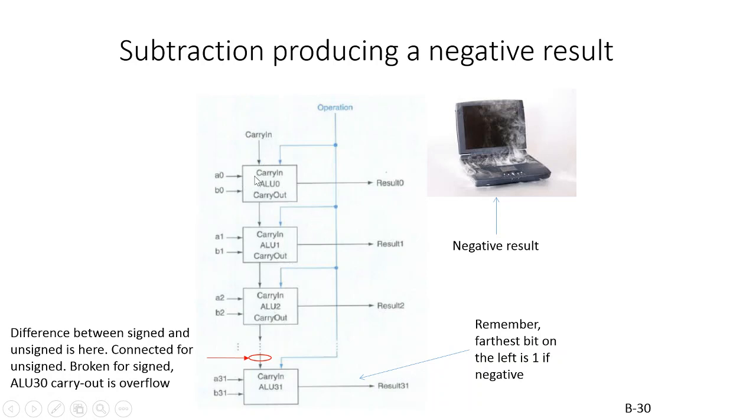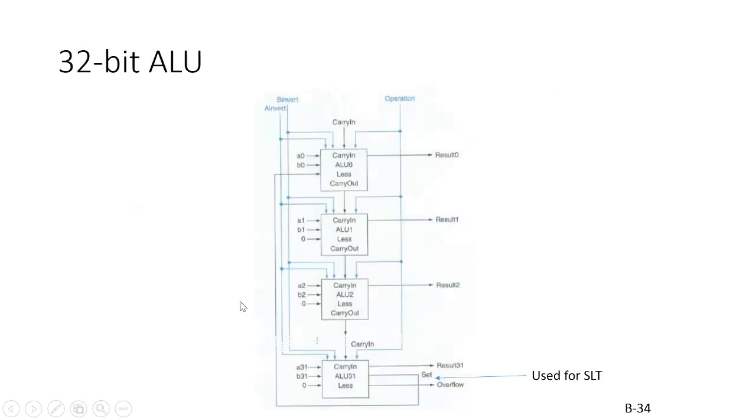Well, this clearly is not parallel, for example, in the way this is designed. But there is another way to design this based on Boolean arithmetic, so that you can deal with the carries and what are called propagates in a separate logic circuit, and do those in parallel with the addition of A and B.